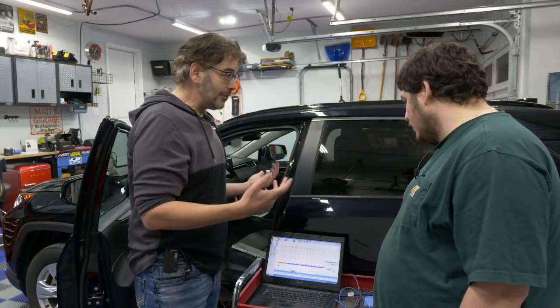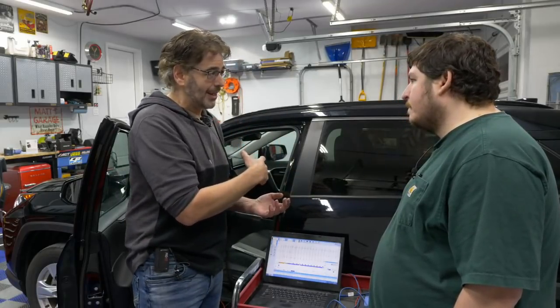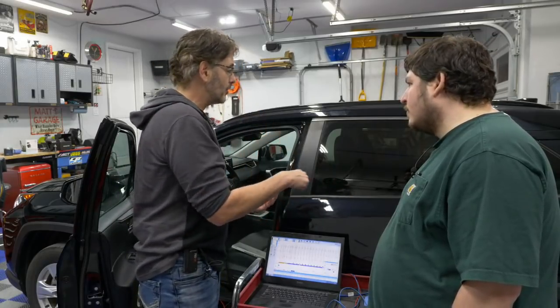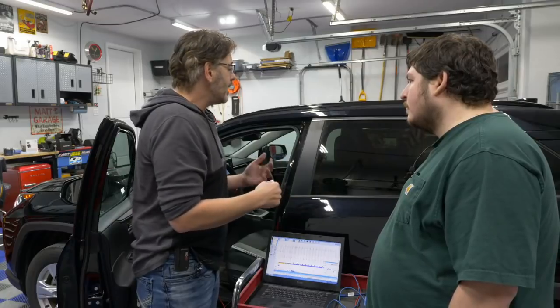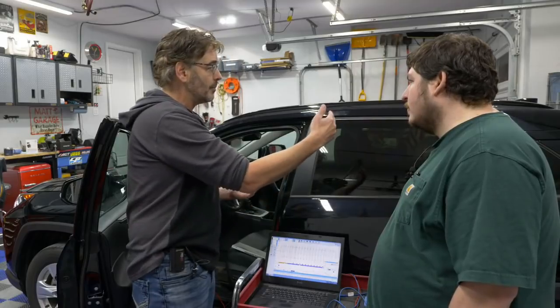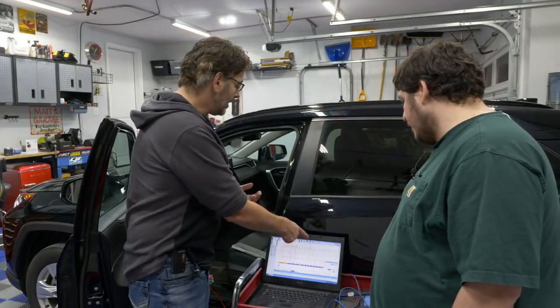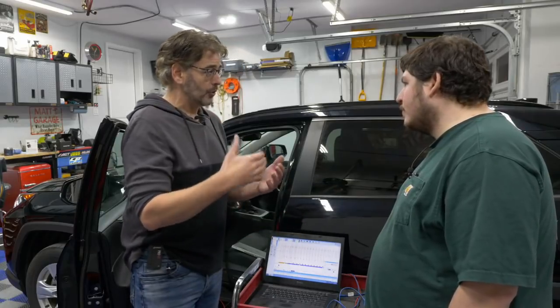It all comes in basically through the CAN network. So my scan tool is getting all the information from the car, all the live data that I've been looking at for years now. And it never really occurred to me, but when I'm connecting into the ALDL, in some cases, on some protocols, it's one single wire that's giving me all the PIDs for my scan tool, but it is data that looks like this, and the scan tool is parsing it out to the individual modules to get those PIDs. Is that what is actually happening? Because it's just occurring to me now.